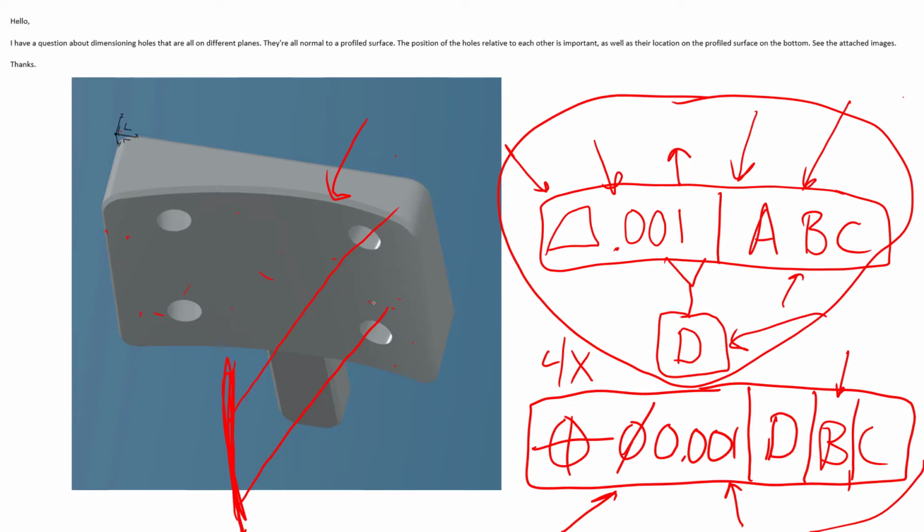You could build a virtual axis essentially to all of these holes, to that axis, to those holes there. And then you have to say these holes are to be in position to that axis. That axis there that I just created is the perfect example, but this is the error that we can have. Then when you go touch off on the surface of your holes and you see the imperfect hole, you're now comparing it to the true position, and you have within a thousandth of that axis to be within tolerance.